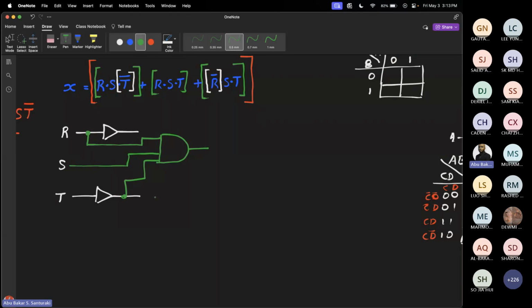The second green AND gate, I put it below the first one. So this guy just has R, S, T. Remember, this is R. So take this, jump over, jump over. The diagram might be a bit messy, so sympathize with me. So that's R. S is this guy. So I can bring it down here, jump over, in, and then T. Not T bar, so T is down here, like so. So this is R, S, T.